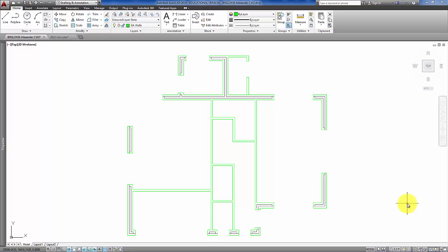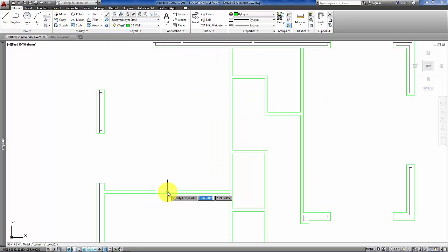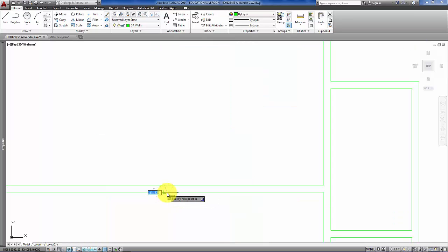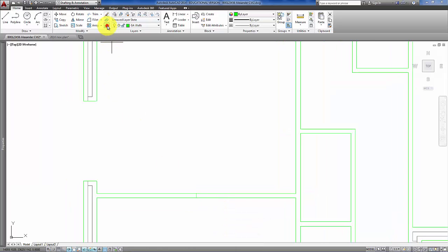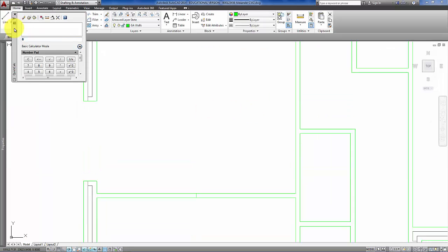Adding the internal openings is similar to adding the external openings, but it's a little bit easier because generally you only have one wall thickness to deal with. So first of all, let's draw a line at the midpoint of this wall. This will be sliding doors between the dining room and the sunroom, and let's offset that half a distance either way. If you are trying to work out half of a distance up here, you can use the little calculator tool just to help you.